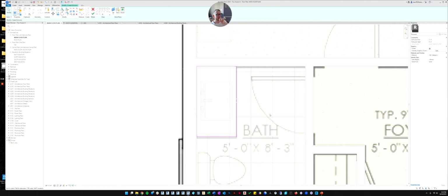And then we want the countertop to be 1.5 inches thick. So we're going to subtract 1.5 inches from 36 inches. So that would be 34.5 inches. So let's put that in. So now what we're telling it to do is, starting at the main floor, it's not going to start the extrusion till 2 feet, 10.5 inches from the floor, and then it will stop it at 3 feet above the floor. And then we can also move down here and we can pick the material if we want.